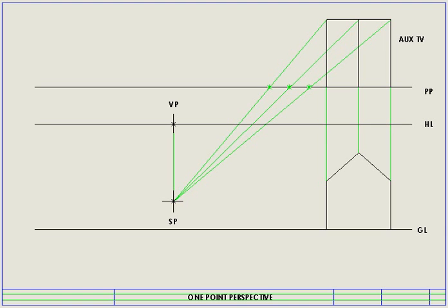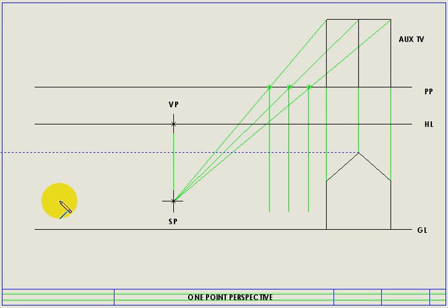Right, then from those points that I've now found on my picture plane, I'd have to go ahead and drop vertical lines. Just take note that if you do it according to the way I'm doing it, and you get all your projection lines done, your drawing will go a lot faster at the same time. Right, and also what I want to do now is connect my front view to my vanishing point.